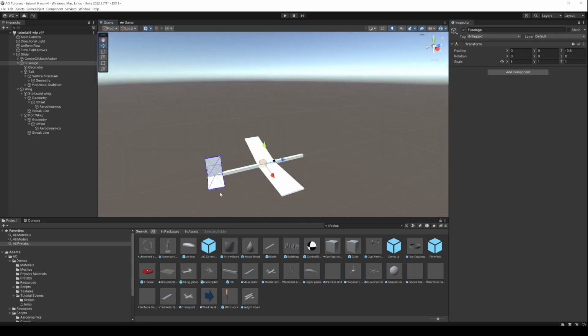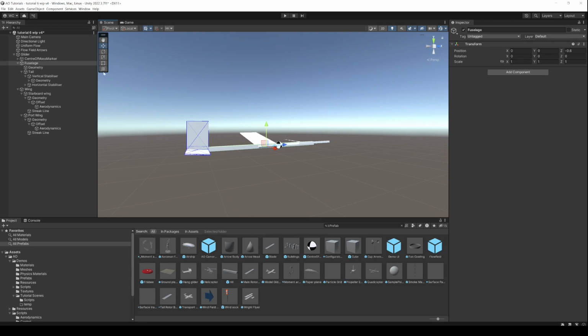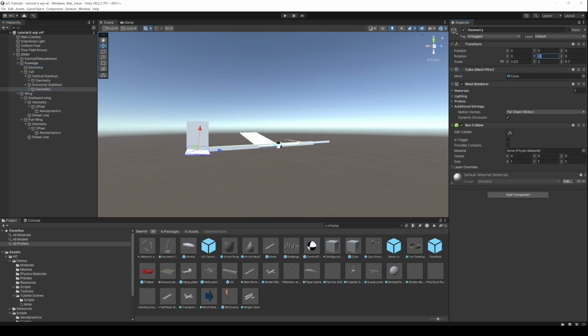Okay, our tail's got some angular displacement in it. Let's just sort that out. So if we go to horizontal stabilizer, geometry, and let's just zero that out. So when we're starting our testing, we're starting at 0. And the other thing I'm going to do on here is pull this out by selecting on properties. And just so we're absolutely clear what's going on, I'm going to call this horizontal stabilizer, so we can control the angle from a pull-out view here.